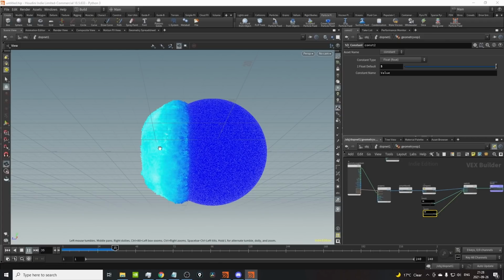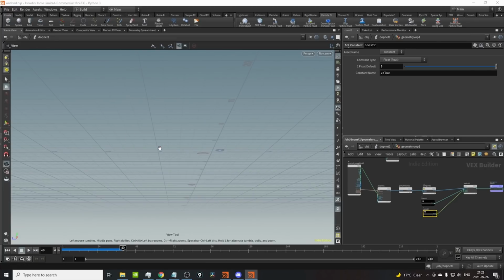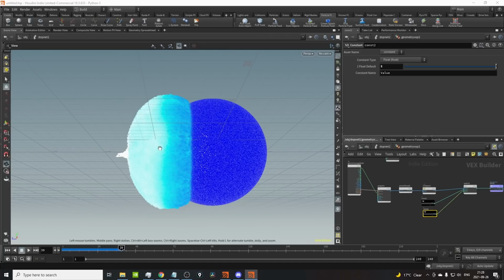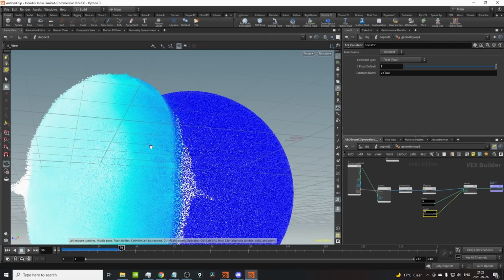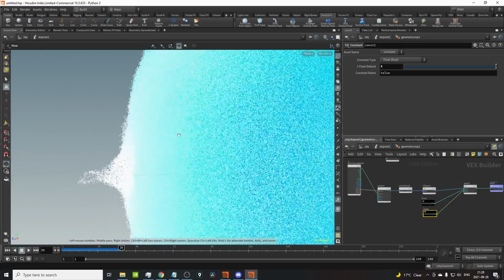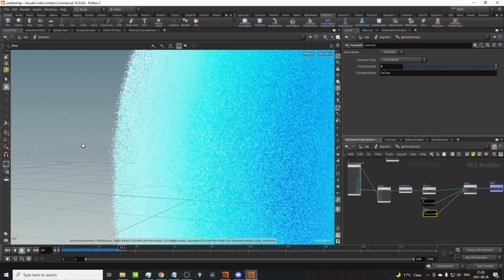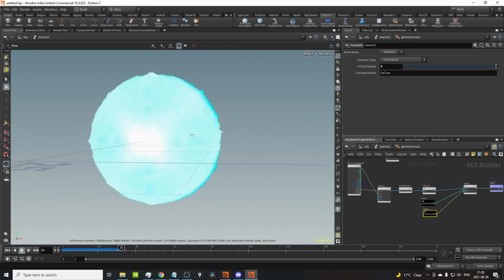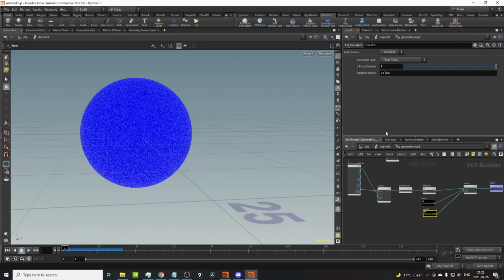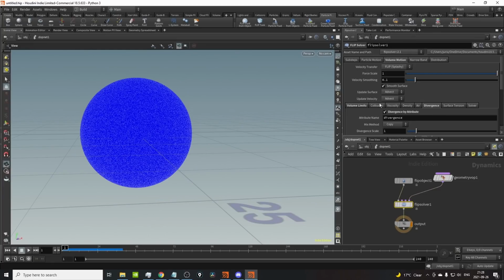And here we see a prime example of a nice little option on the flip solver, which I waited to get to until now, which is called receding. It's godsend and devil send at the same time, because we have this little eggshell, right? But here it's making this big poof of particles, right? Which is very, very strange. And the reason for that is receding.